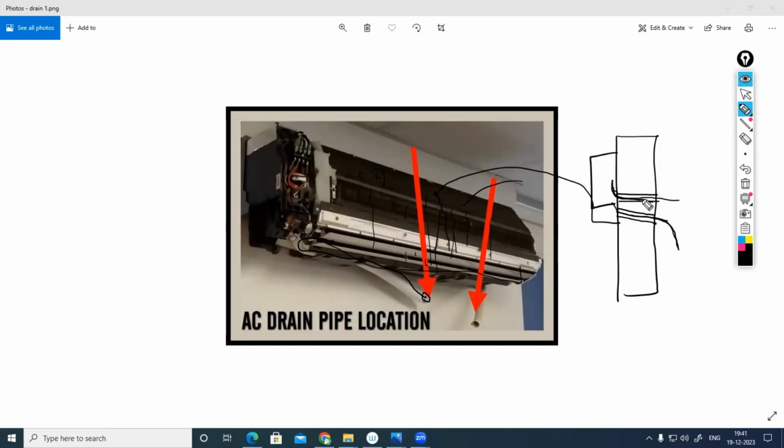That's why, if you're not maintaining the proper slope, the contaminations will accumulate somewhere here, no? So eventually a block can come, a leak can come. That is another story. So instead of taking the conventional PVC flexible pipe directly, we can provide a rigid PVC sleeve there. Means if you want to take a 32 mm flexible pipe outside, use a 50 mm sleeve before doing the plastering.